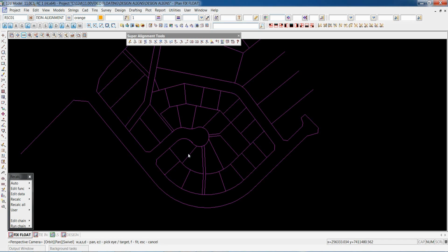Fixed parts are set in geometry and are not dependent on any other element in order to solve. Those would be things like fixed lines. They can be defined by 2 coordinate points or a coordinate point and a directional bearing. A fixed arc can have the center, ends and radius values set. It can also pass through 3 points and also have a start point, radius and a direction. But they are fixed in space and, as said before, are dependent on no other element.